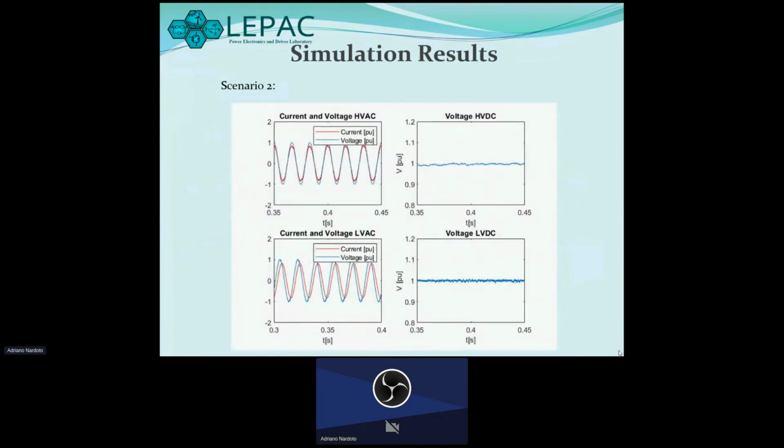The results demonstrate that the power factor at the grid is unitary, showing that SST has an important function as a reactive compensator for the microgrid. This reactive management can be achieved by the proper control of quadrature current at the SST rectifier.